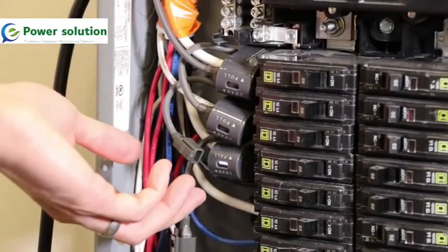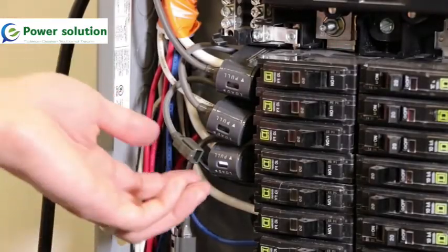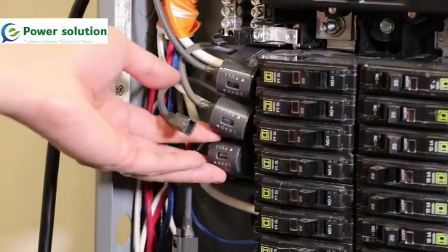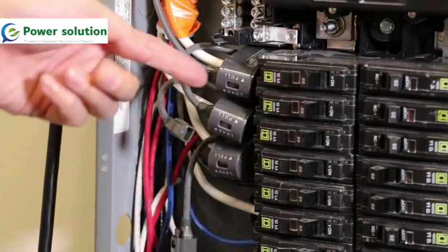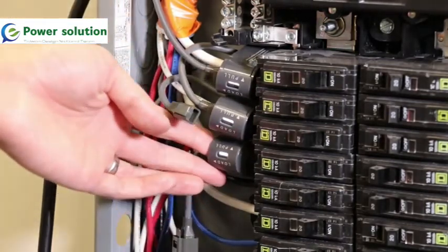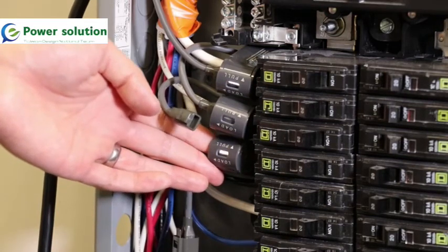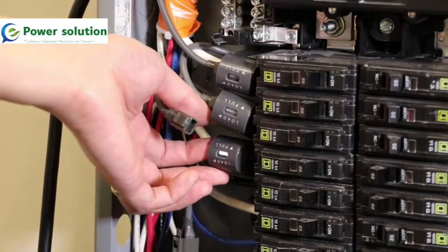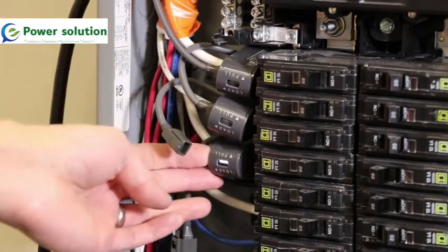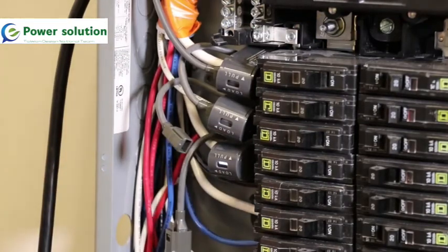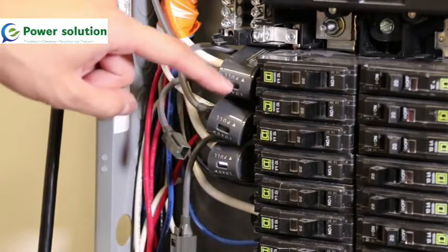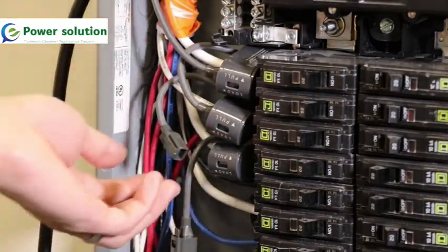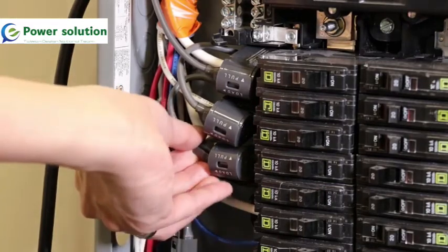So let's introduce a fault and see how we can detect it with the system. In this case, we've missed one connection. During the self-check of the CT, you'll see that each CT will perform its quick flash diagnostic as normal. But you'll notice the first few CTs in the chain will extinguish their light as if they've passed, and at some point, these CTs remain lit. The change from good status to error status indicates approximately where the fault is. In this case, it's obvious, and we've missed this cable connection.